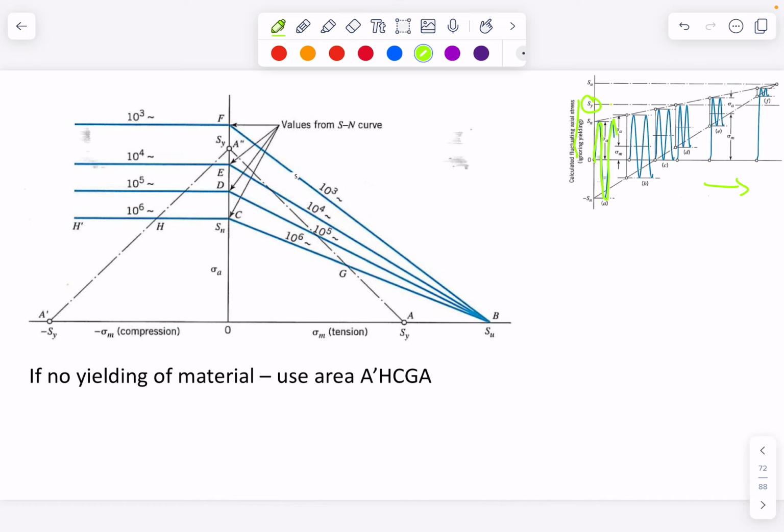Noting here is the yield strength out along there. So this guy on first stress is going to be okay, and he keeps just missing that yield line. So I'm not going to yield it, but I'm running it at a higher average stress level. Sorry, that's sigma m there, sigma m and sigma a. But if we come over to here, I've immediately yielded, and I'm going to continue and then put that on it, and I'm still going to get my 1 million cycles worth of life out of the thing.